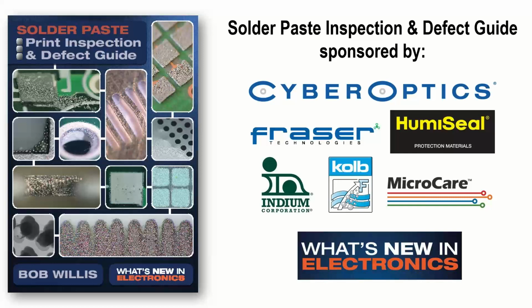Is there any way to reuse paste? Oh no, I've answered that one. How often should I replace a squeegee? Well, it's about damage. A squeegee blade should perform, and just like a stencil, how often do you change a stencil? Well, you don't. It's only when the stencil is starting to give you a problem, i.e. it's damaged in some way. And if you do your quality control checks, it shouldn't be a problem.